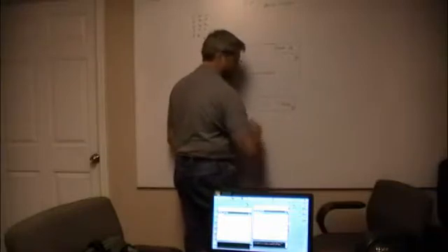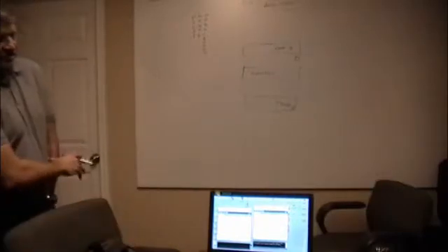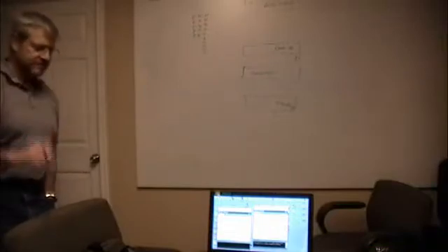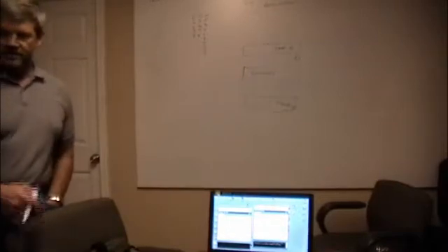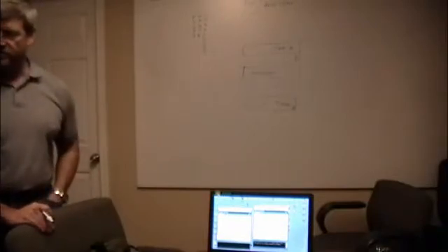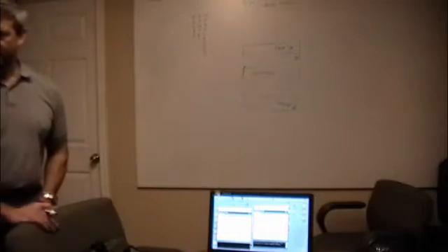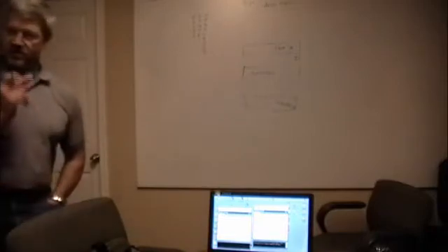What do we have? Pulse Width Modulation, Servo. Okay, so we've just been doing lighting LEDs and making them change brightness, talking a little bit about the tone function, sticking with pure Arduino libraries and how they work, but also showing how other things work. The first thing we did was a coded PWM, where we actually wrote code to do a PWM. And now I'm getting into the actual hardware, saying this is what this hardware does, and this is why you can only do it on these pins when you do analogWrite. We did an analogWrite also.